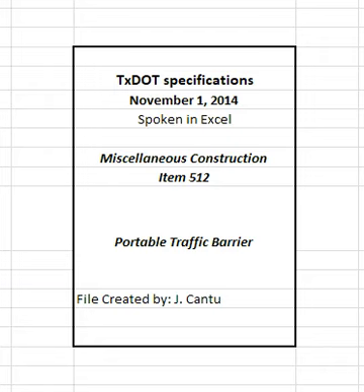2.2 Furnished by the department. Department furnished barrier sections will be at a stockpile location or an existing traffic barrier installation shown on the plans. 3. Construction. Notify the engineer of the location of the casting site and the date on which the work will begin.